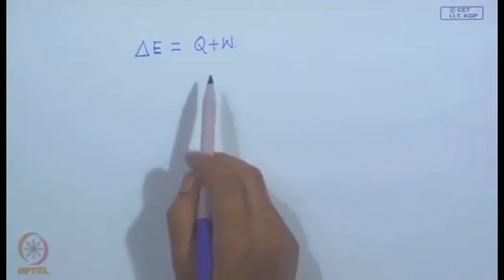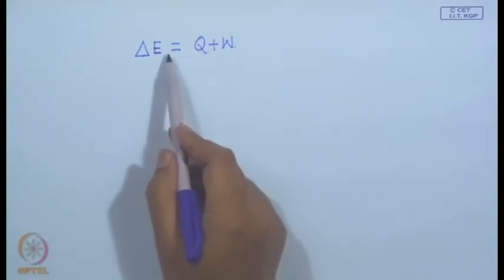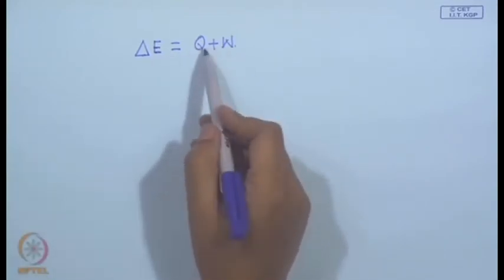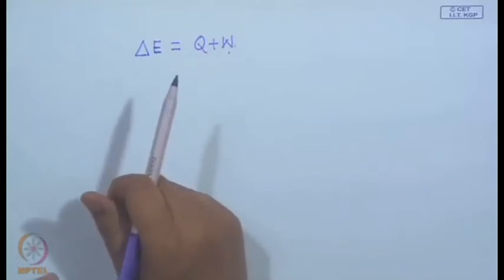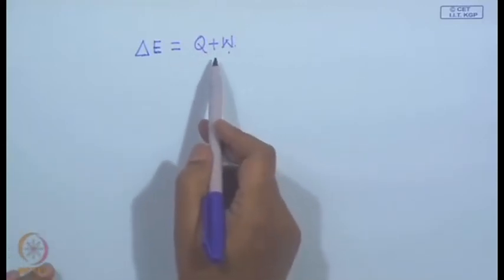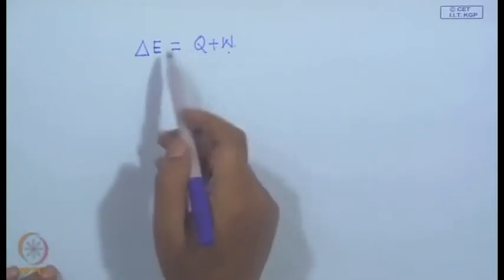However, the amount of heat added and the amount of work done are measures of external effects, and each of them depends on the path in which the transition has taken place, that is, the change from one state to another. However, the law states that the sum of these two path dependent variables is independent of the path.